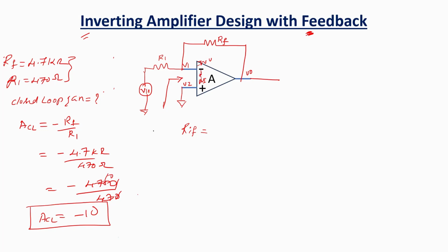There is a high resistance which is present across the terminals. This is nothing but a very high resistance value, which is in parallel with this particular resistance R1. R1 is always low when compared to this huge resistance. So in this parallel combination, any high resistance value in parallel with R1, the resultant will be very close to R1.